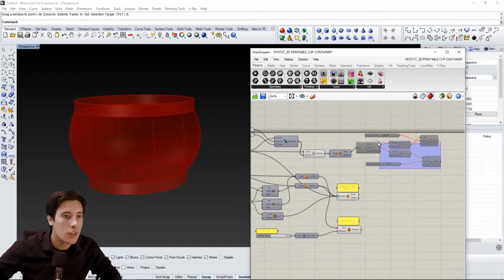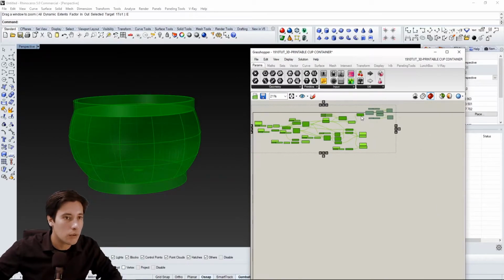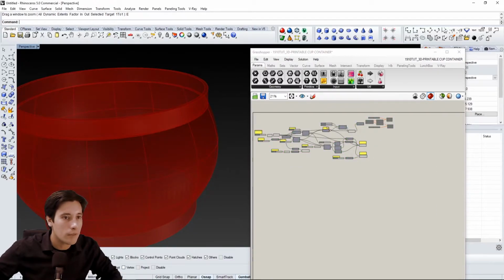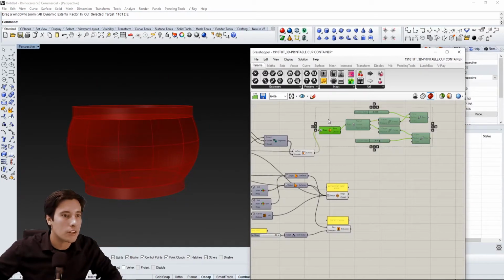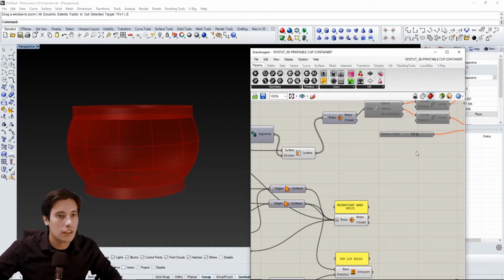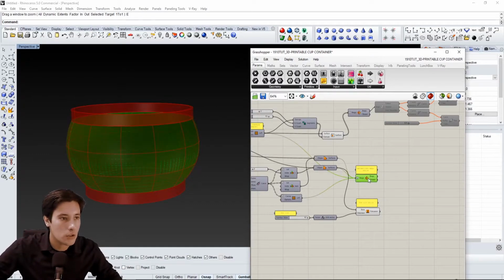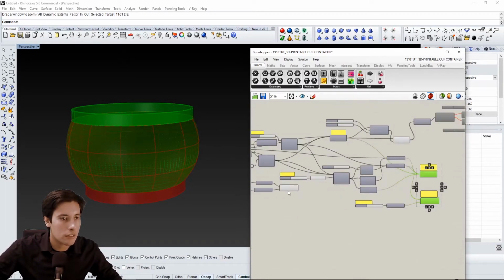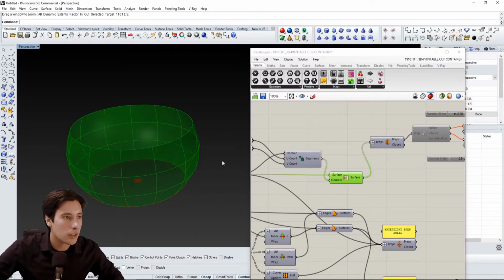And then I'm going to show you another way of creating a cool pattern using this base geometry, but we're going to do it right next to the other pattern, just so you can see in contrast how much work it takes to do the one before rather than the one I'm going to do right now. Okay, so I brought all of these back, but I'm actually going to select them again, do a space bar and hide. And I'm just going to be working with this iso trimmed surface that we had before.